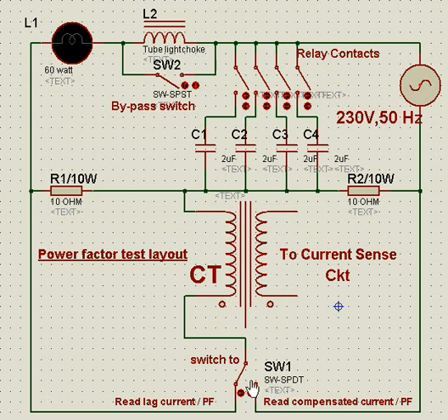And when this switch switches to this side, the CT gets connected between this and this point to measure this current. But in a situation where the capacitors are not connected, this current and this current are all same. After we read the inductive current, which is sensed by the CT and given to the control circuit, the capacitors will come into the picture automatically.